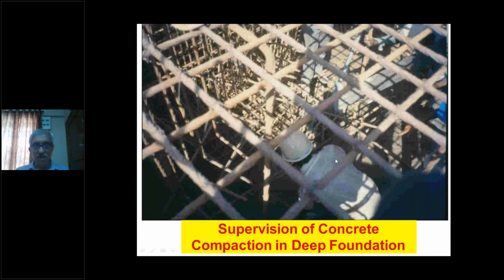It is very, very important that the person who is handling the needle vibrator and the person who is supervising actually observe the flow of concrete below the bars so that later on no corrosion can occur in the foundation. This is very important, but make sure that the persons come out of the concrete when you are finishing the concrete. We don't want too many footprints in our concrete.